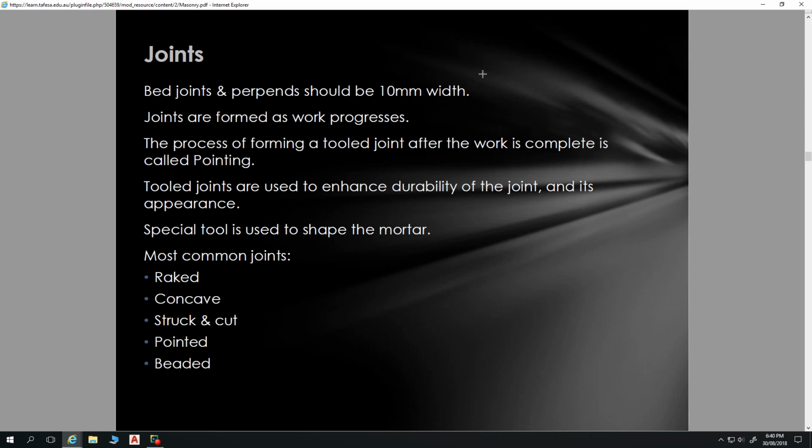Where you differ from that, and actually, this comes into brickwork dimensioning. So I said it's really important to know the standard size of a brick, the 230, 110, 76. One of the reasons for that is not only so you can judge the height and so on of a wall, so you can look at a wall and go, oh yeah, that's 4.3 meters long because I've counted this many bricks, etc. That's good, but as designers, what you don't want your bricklayers doing is just cutting lots of bricks.